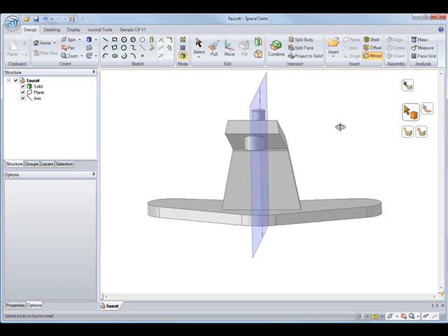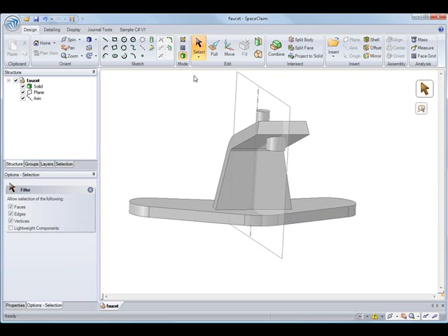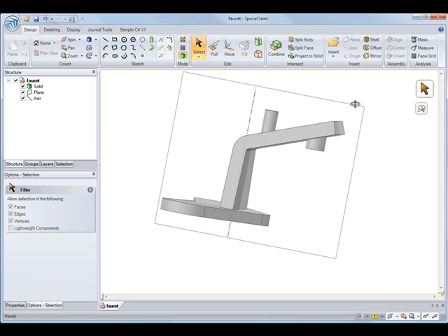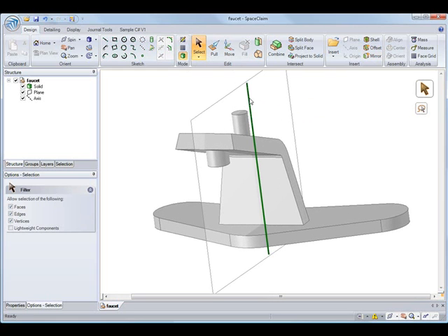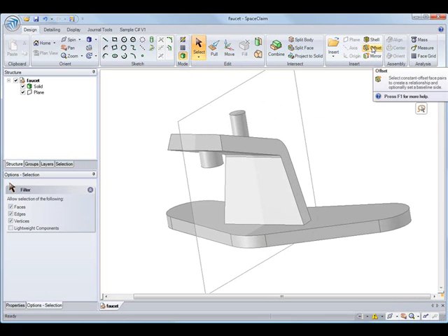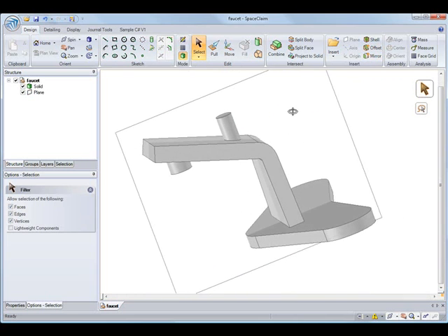to the other side. And you can see that the draft that I made on the spout is now mirrored to the other side. And actually, our entire part now has a mirror association. So if you make a change to one side, the other side will update. So let's focus on offset.